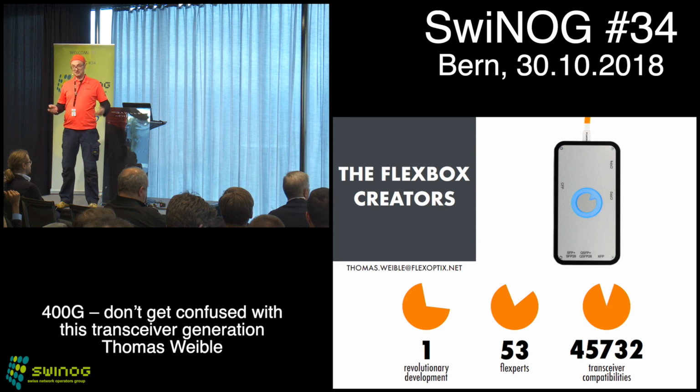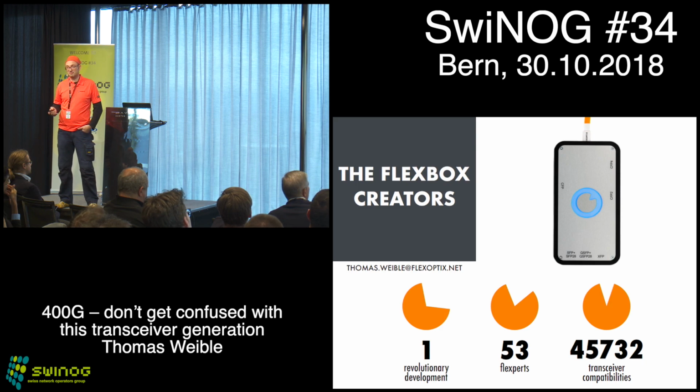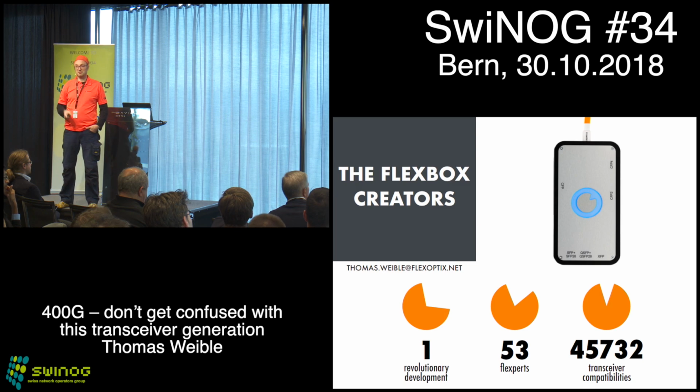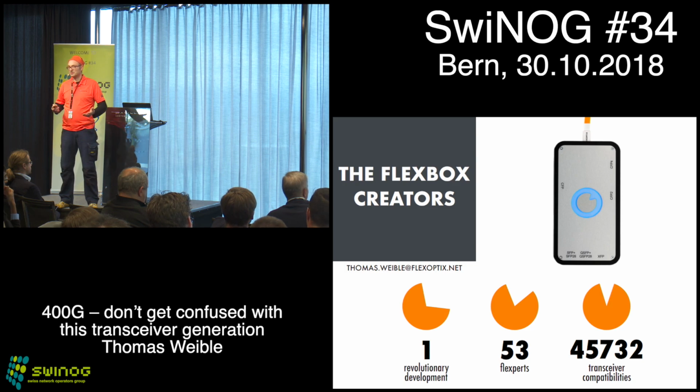That still gives us a lot of freedom to do the programming on the transceivers itself. We have done that for the 100 gigabit, for example, because the good thing also for us is there is still a microcontroller inside of those transceivers, so we can still tweak that microcontroller. We have done that for QSFP-28s already, for example, getting ER4 transceivers able to run 30 or 40 kilometers, getting them up and running in legacy gear, or gear which is intended to only support up to 10 kilometers. That's basically how we did it, by changing the configuration of that microcontroller.